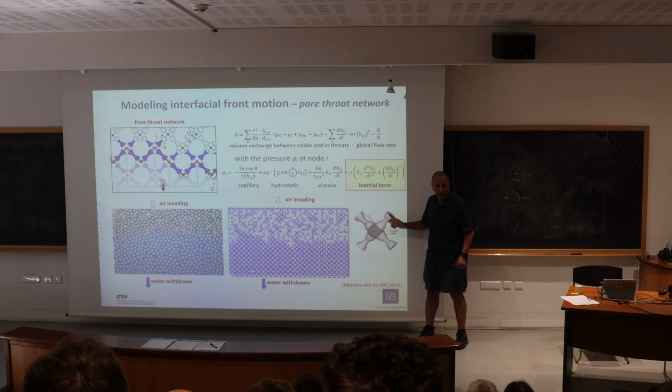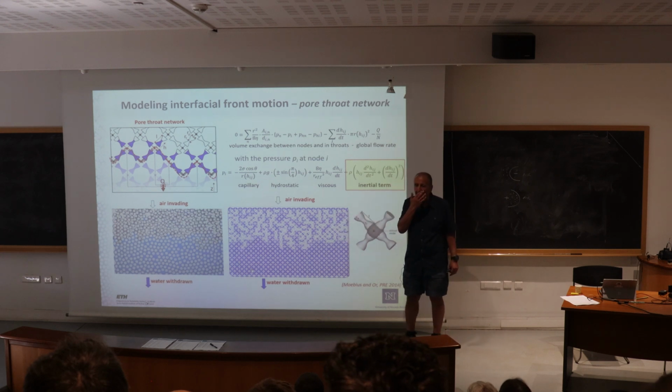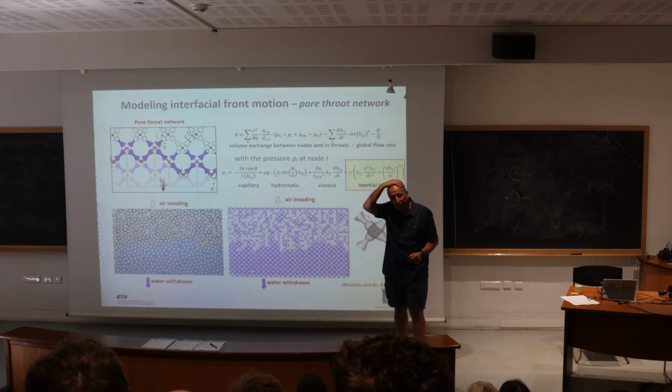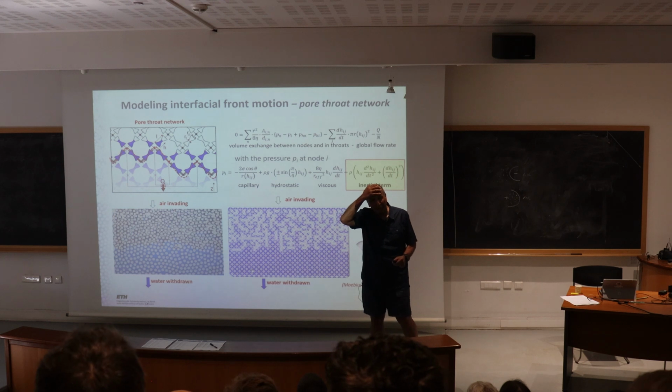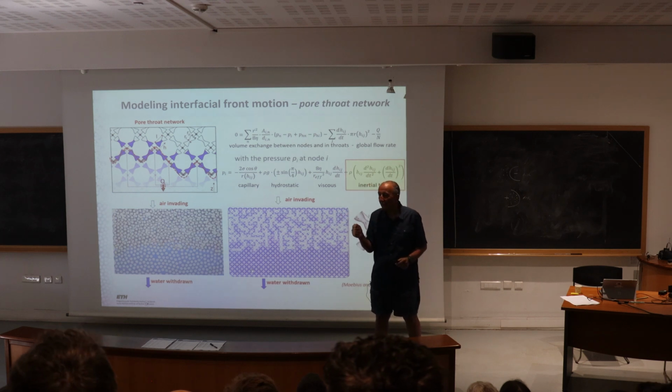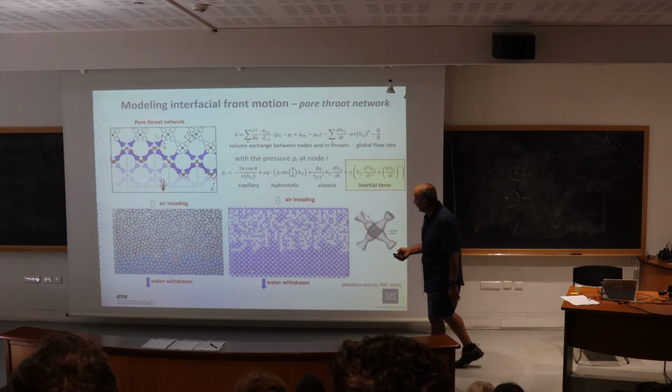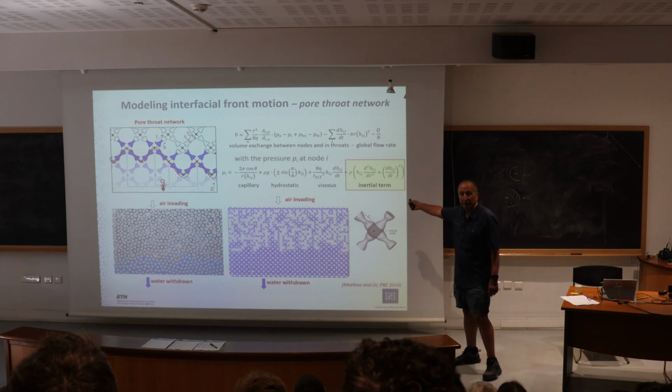So basically liquid is distributed to the other throats as soon as conditions are favorable. And you can see the behavior is quite similar in terms of the jumps to that of an equivalent porous medium. The reason we wanted to do this throat network, not pore network, is to be able to see the effect of inertia. Meaning, in the real world, I cannot turn off inertia. I can only turn off inertia when I have a model, so I can compare the outcomes with inertia and without inertia. Okay? And this is again the inertial term for you, Kevin.